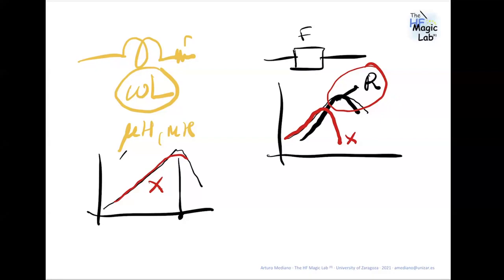So the activity that you are injecting from the device to the heatsink is returned to the ground of the power system. But obviously, you can have some problems, for example with safety or immunity tests, and then you need to apply other solutions. But the idea is to put the heatsink at a constant voltage, so it is not floating and not experiencing dV/dt.